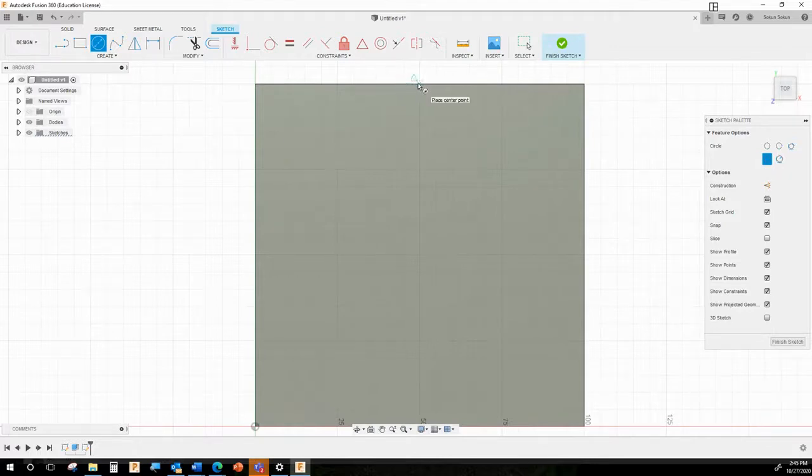And when you're in the middle of an edge, it actually gets a little triangle to let you know you're in the middle of the edge. Just a kind of fun thing you'll need from time to time. So I'm going to move down here to the center. I'm going to click and drag, like always, with my mouse button held down. And then I can just let go of my mouse button. And I want this to be 30 millimeters.